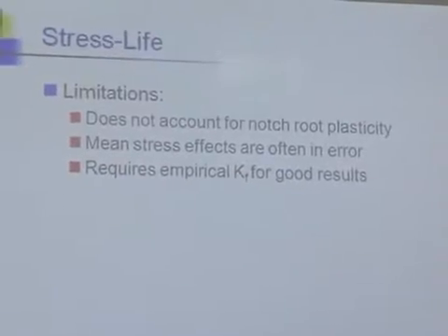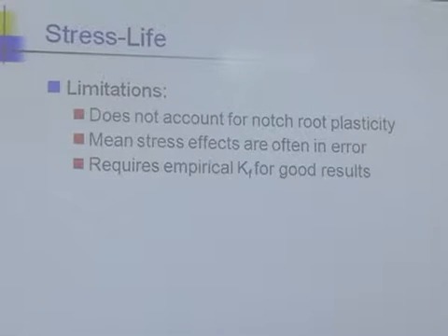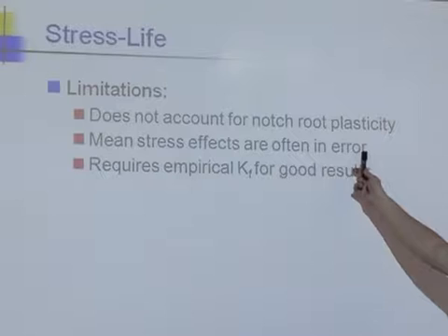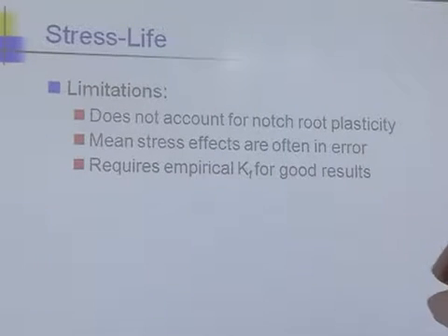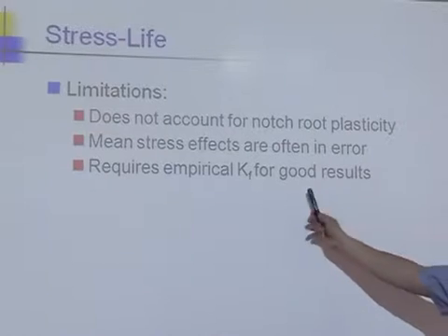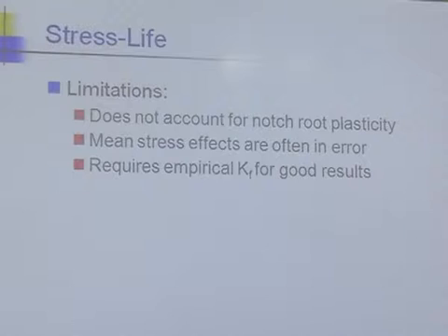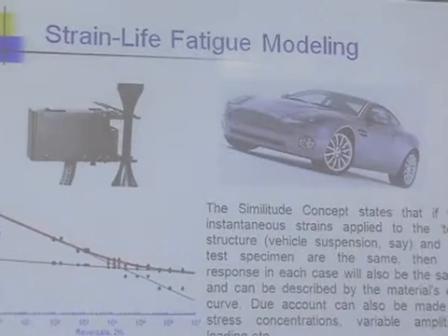So, limitations. We already talked about this, but in many situations you have plasticity. And if you get the plasticity wrong, then frequently the mean stresses are in error, sometimes of the wrong sign. And of course, a limitation is you really do need to understand what happens around stress concentrators, gradient effects, and all those kinds of things. So that's the stress life approach.